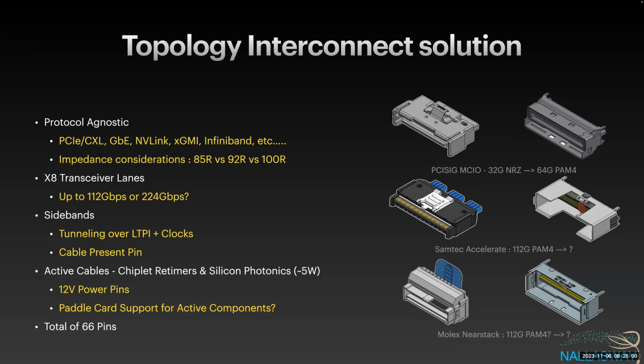basically, I'm starting to think we possibly want a connector of our own, or to leverage an existing connector that can serve our purposes. What we've investigated so far in this module standard is obviously the PCI SIG MCIO. That's CXL in PCIe going forward. That's at 32 gig NRZ right now, and I think there's a pathway with this connector to 64 gig PAM4.